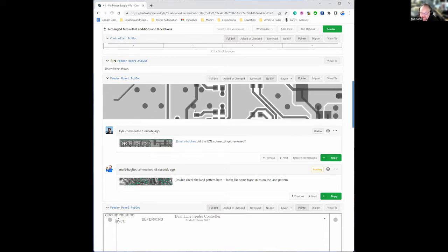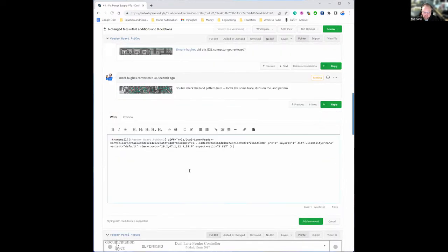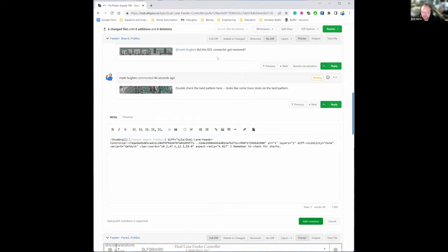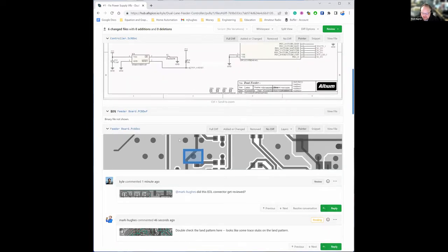Here it looks like we've got a trace intersecting a via. That might be something that we need to look at to make sure that the via is not accidentally creating a short on the trace. So I'm just going to snip it there and see if that doesn't accidentally create a short circuit. It might not if they're on the same net, but I don't think they are. Do we know which is the...